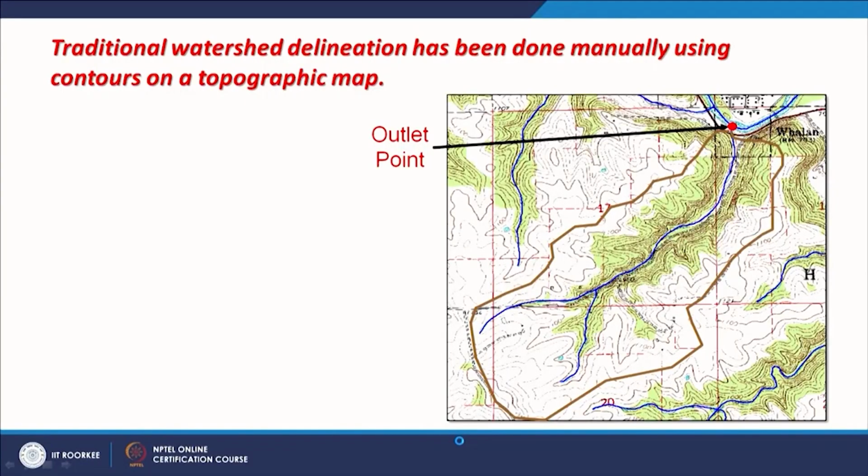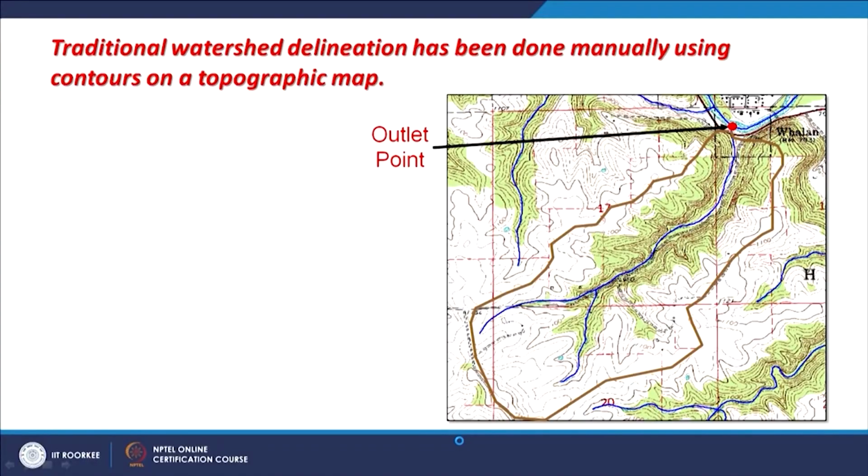Now as I have been saying, it is a topographic divide. Watershed boundary is also a topographic divide. So if you see a topographic map, wherever you have higher points or contours like this, or spot heights are also there, then that becomes the watershed boundary. So using a topo sheet and with some care, we can definitely draw a watershed boundary quite easily. But if we have GIS and a digital elevation model, we can do all these things very accurately and automatically through this surface hydrologic modeling.